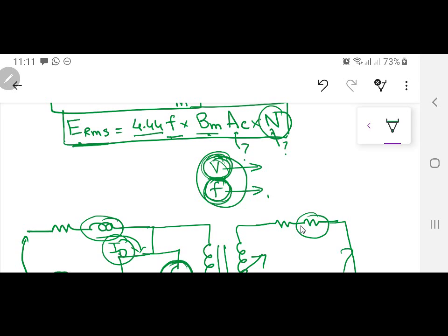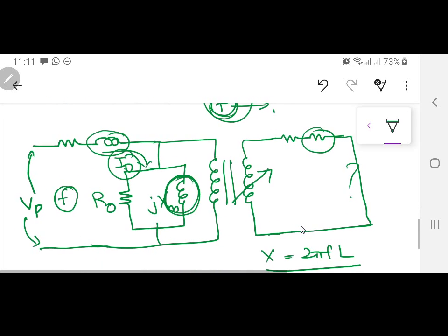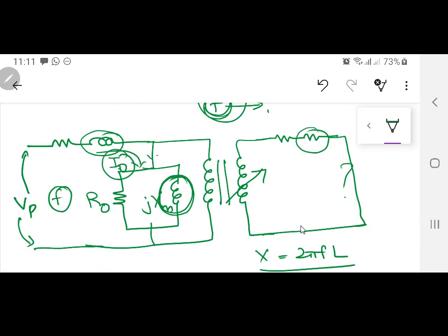अगर आप voltage reduce कर रहे हो तो frequency को भी reduce करना है, so that the same amount of I0 flows over there. अगर आपने frequency reduce नहीं की तो क्या होगा? I0 करंट कम होगा, मैग्नेटिक फील्ड कम प्रोड्यूस होगी इंडक्शन मोटर के अंदर. और ये I0 कौन सा फ्लक्स है? जो एयर गैप के अंदर होता है मशीन के अंदर. तो जब फ्लक्स कम होगा, मैग्नेटिक फील्ड कम होगी, the motor is not able to produce the same amount of torque.